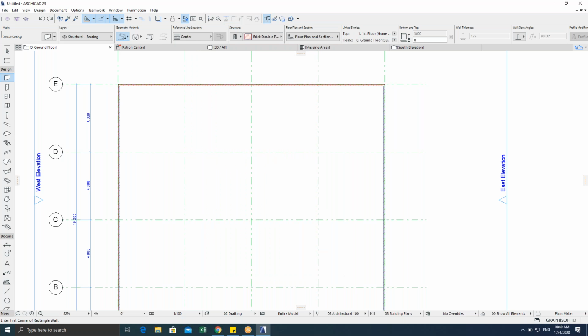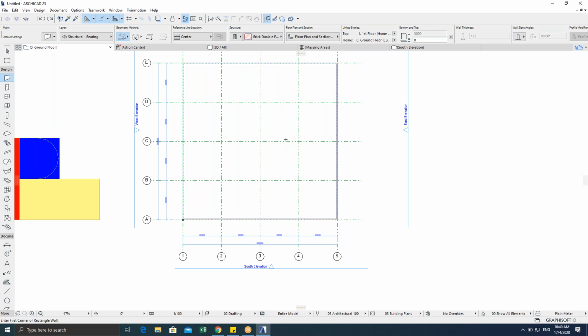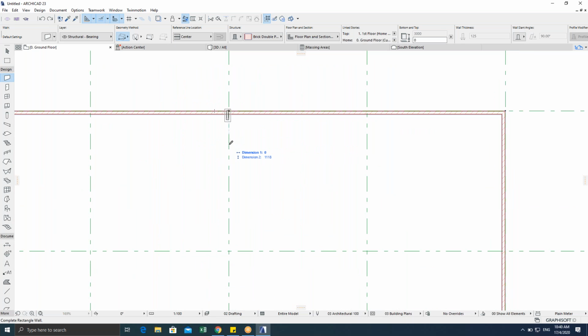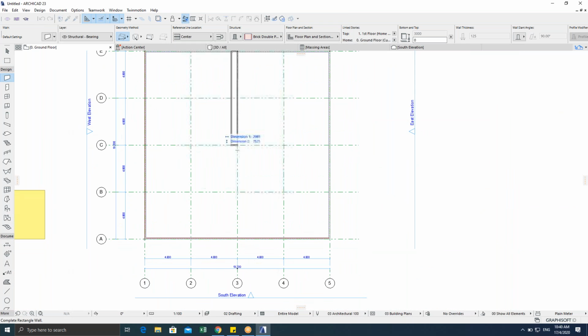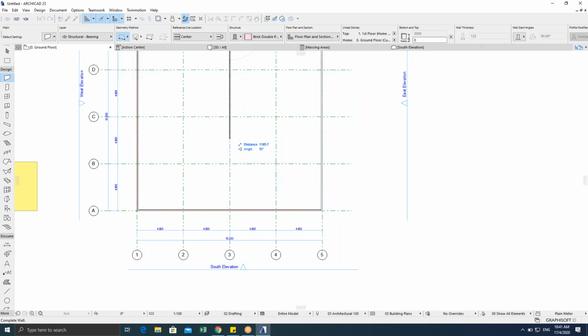And click OK. Then you can create your own building, but I just use a simple one for us to understand. And then under geometry method, I just choose this single straight line.